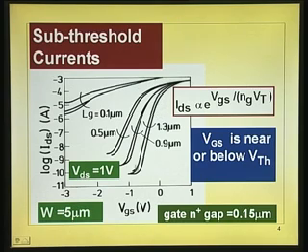So, they are not falling by 60 millivolts. See, how many decades here? This is about 6 orders of magnitude down from here to here. 6 decades. These are all decades. 10 to the power minus 4, minus 5, minus 6, minus 7, minus 8, minus 9. So, if you take 10 here, 10 minus 6 is 4 there. So, that is falling by 6 orders of magnitude.